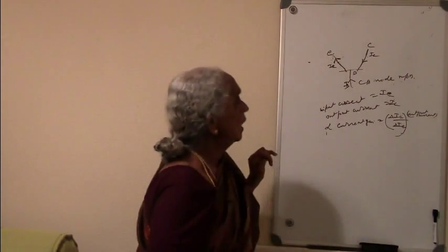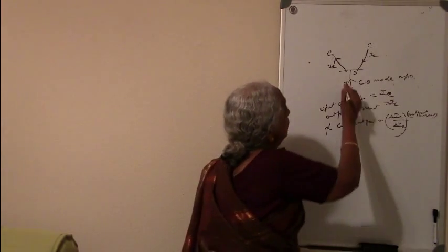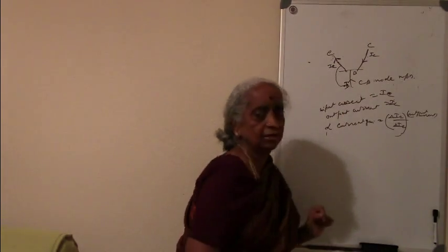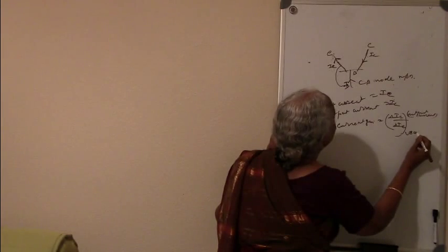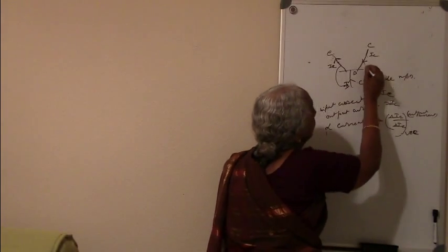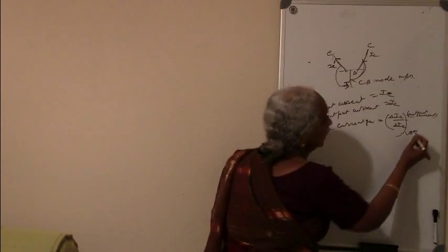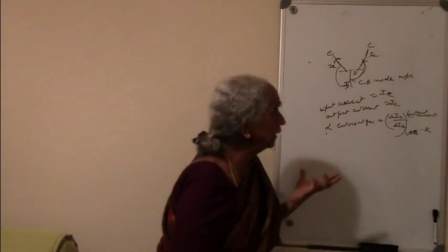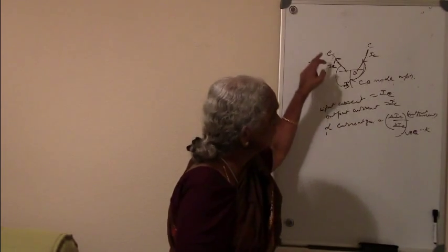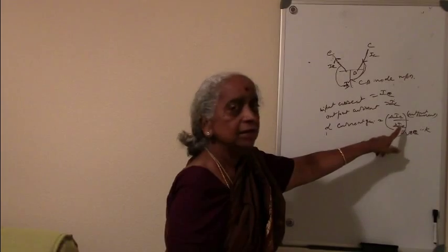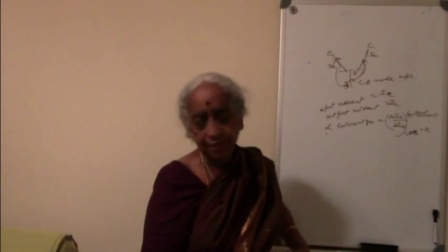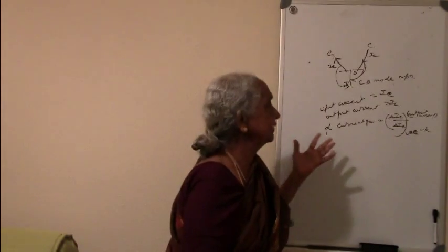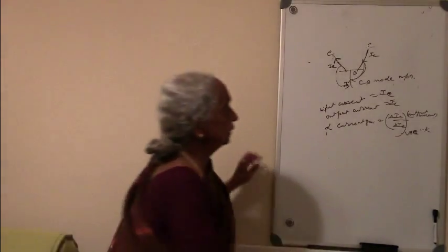Here, in the common base mode, VBE is going to be a constant. So for a common VBE or VBC, this one between base to collector, if you keep that constant, and you somehow increase your IE, what is the change you get in IC? The ratio of delta IC by delta IE will give me the current gain. Yeah, it will be my alpha.